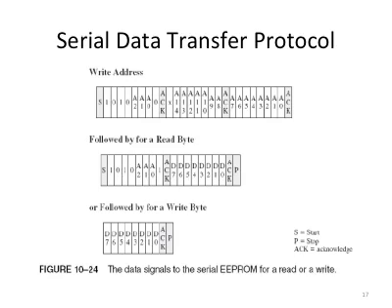With this series of ones and zeros, we are saying, I want to access EEPROM 000, and this is the address I want to access. So this is to give the address to that chip.